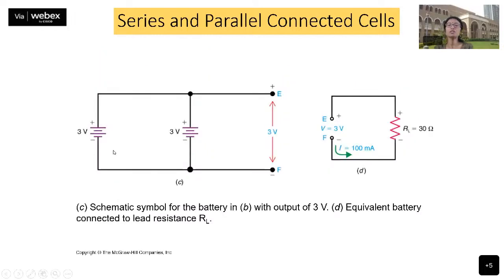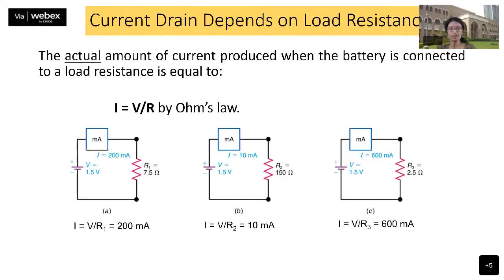If you need more voltage as well as more current, then you will generally put all these cells in a combination of series as well as parallel connections, so that you can do the maths and connect all these different cells. And this will lead to your battery.